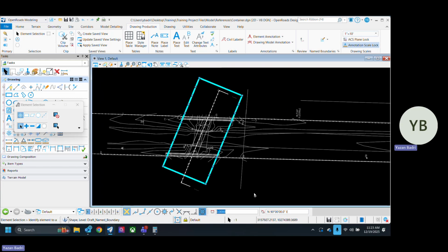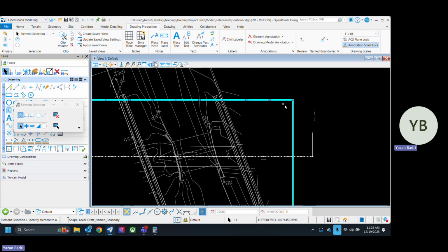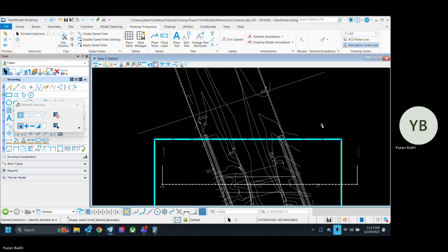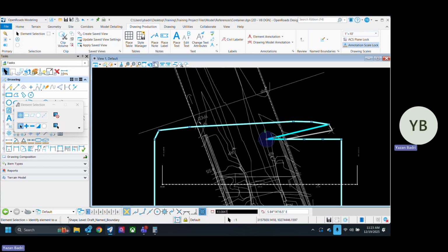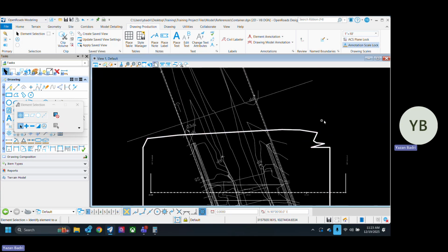All right, you see this? This box. This is the one that's in my sheet. So see, we're slightly off. Those vertices, I can just move them like this. I mean, this is a no print kind of level. So I can just do this. It's okay. Is it going to show up like that? The sheet, yeah, but when you print it, this is on a no plot level, so it doesn't show up.